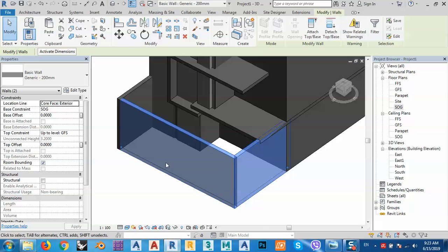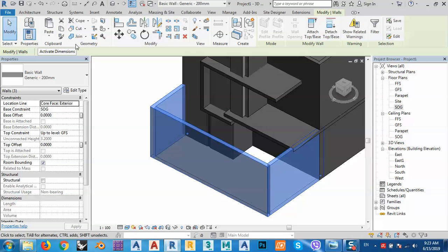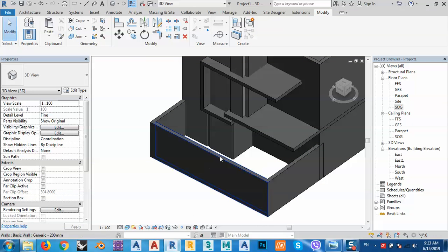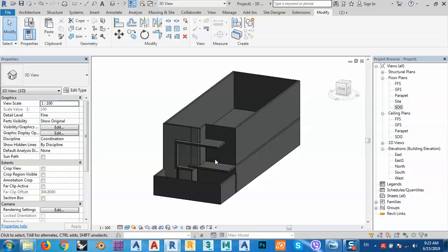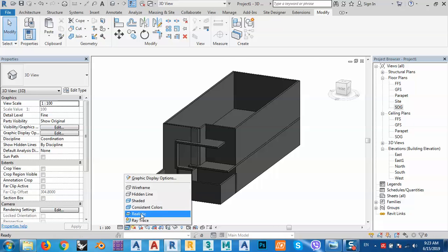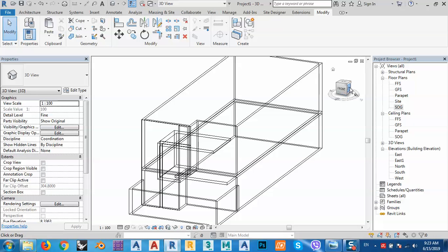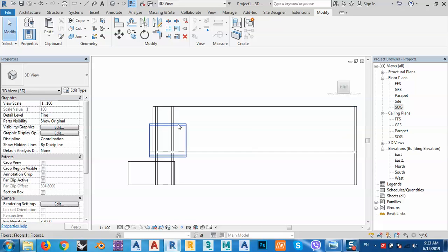but now we know that this wall is not like other walls, so we have to say unconnected, and for the height, let's say 2.2 meters. Okay, it's just like this. So we see here, we see everything here. Okay, I think we have some problems here, let's see, good wireframes. Yeah, we have to raise this one till the level 2.